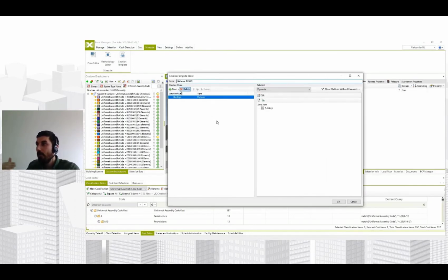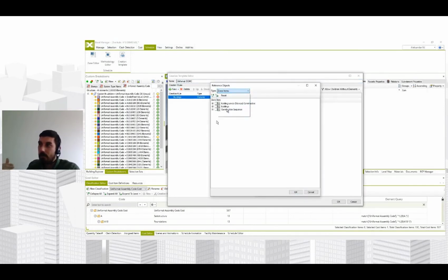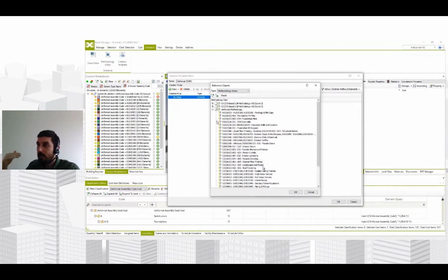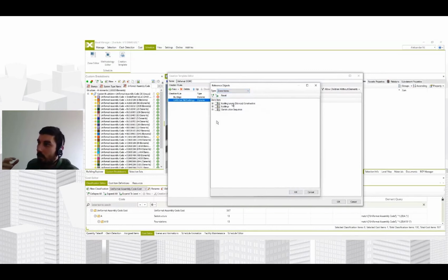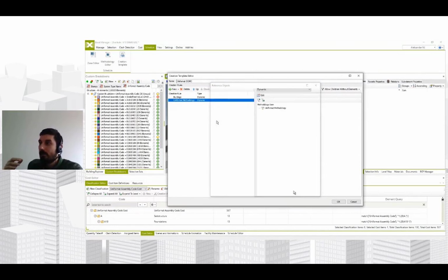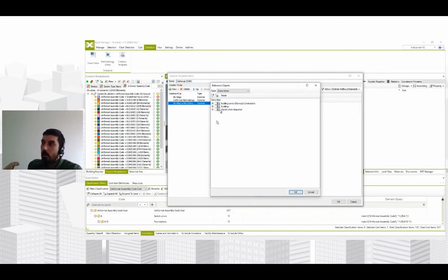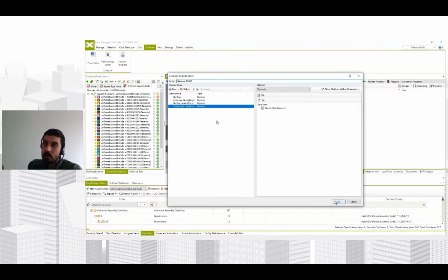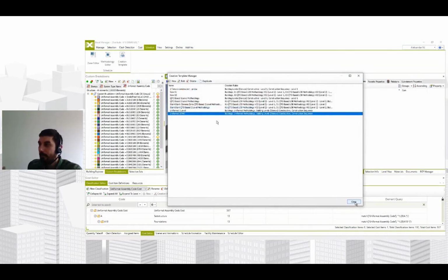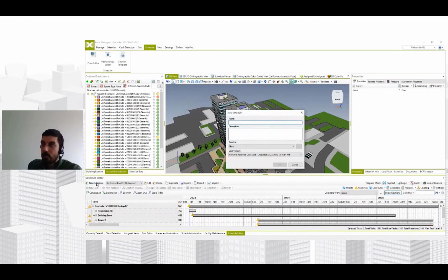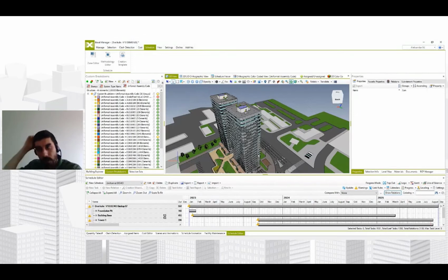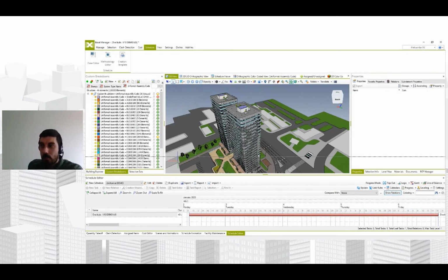We're going to say, okay, first we want to organize model elements by buildings, then by the methodology that we have created. Then we're going to distribute the works on the levels, and then on every level we want to distribute it to the construction sequence, to the phases, let's say. And now we can just go to the schedule editor, create a schedule that is connected to the cost version that we have just created, the cost classification. And we can again use the wizard.